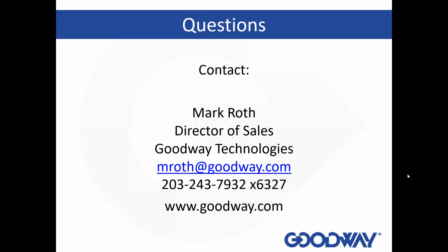Yep, with different types. I'm not familiar with that specific name of boiler manufacturer, but with different shapes, there are different tools that you would use for cleaning it. Sometimes you want to use a straight punch, and sometimes you're going to use a rotary machine with a specific type of brush or tool that will kind of thread itself down the tube when you're cleaning it, or be able to make those tight bend radiuses if you need to.